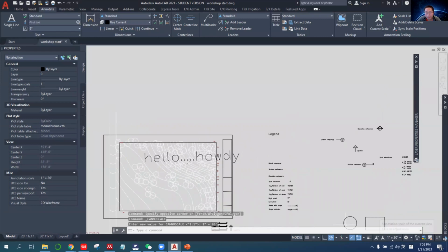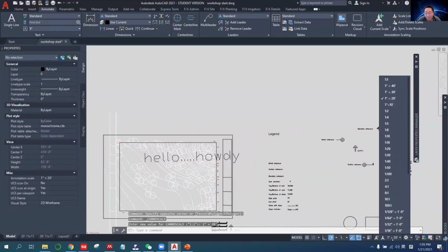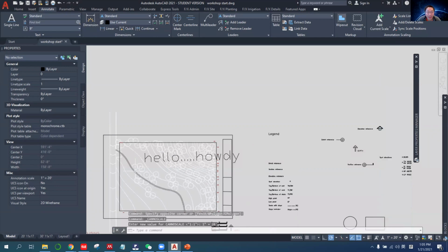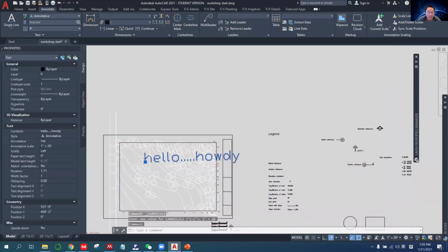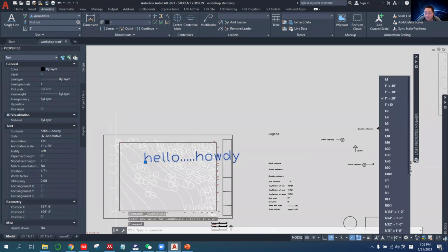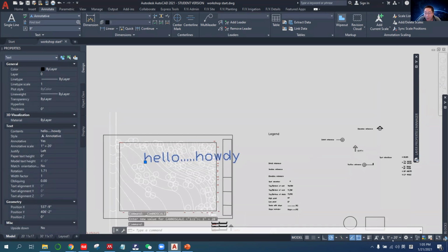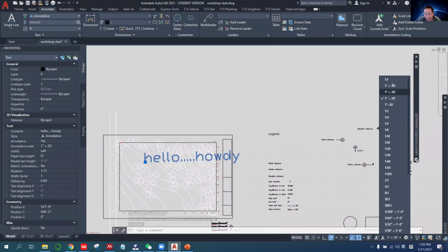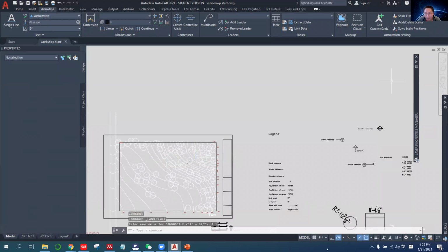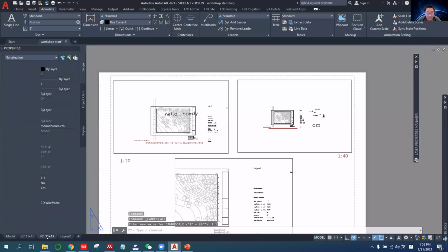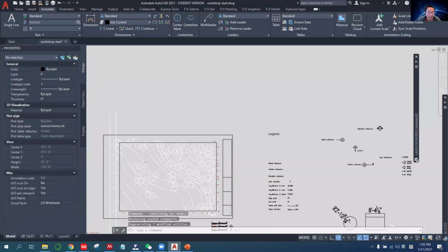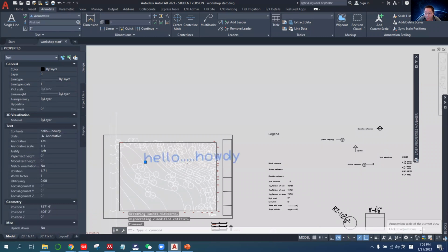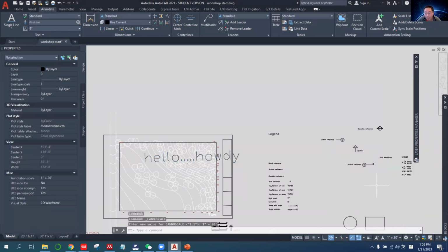So just always remember, the size of annotative dimensions is paper size, and it changes. In model space, you will change size, but in paper space, they won't. See how small that is. That's why you usually have to go back to one of the scales over here.